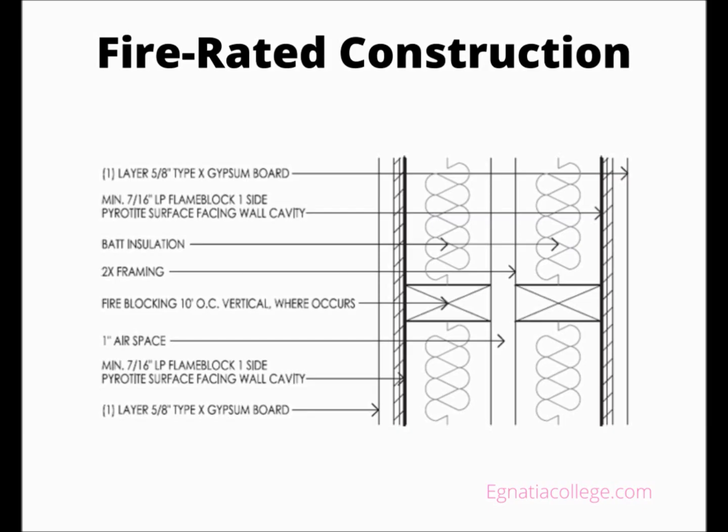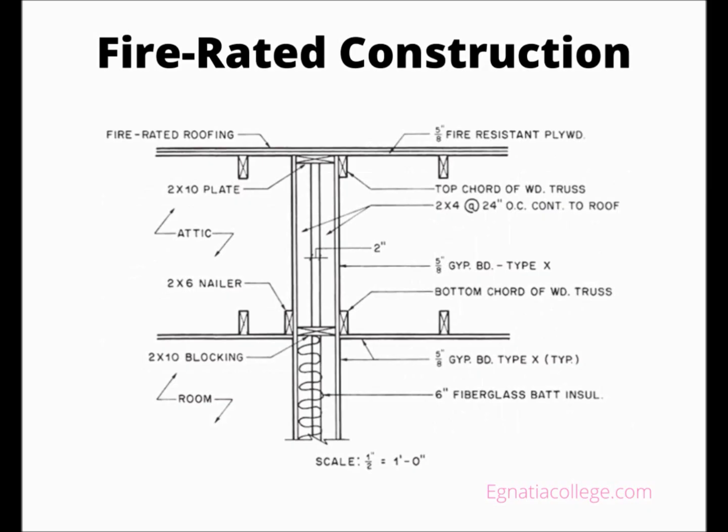Fire-rated wallboard is used where a fire-rated wall is required. Fire-rated gypsum wallboard is Type X or Type C wallboard. Varying degrees of fire resistance can be achieved by using a second layer of fire-rated drywall on one or both sides of the wall. Other materials, such as OSB that has been treated, may also be used. Fire-rated construction is frequently used to separate garages and mechanical rooms from living spaces. Party walls are also fire-rated to prevent a fire from spreading between housing units.